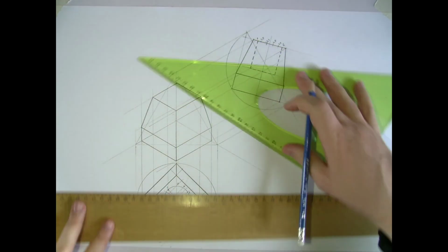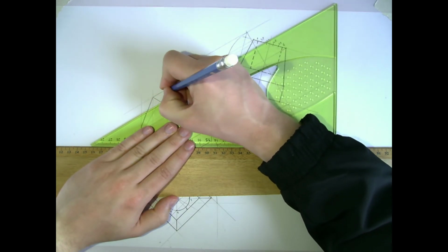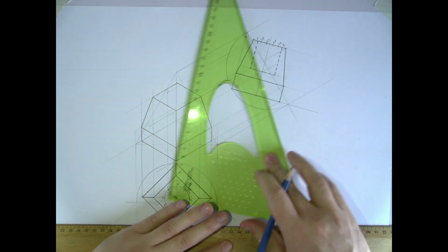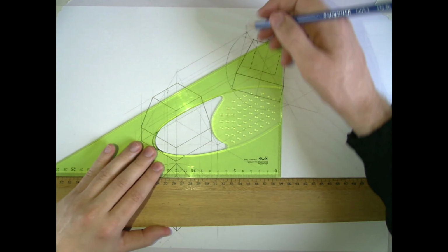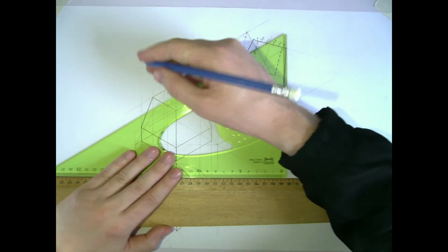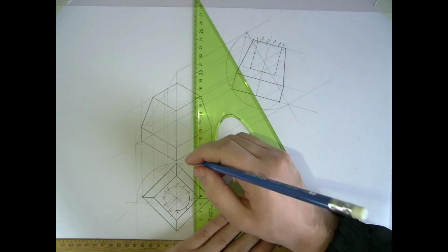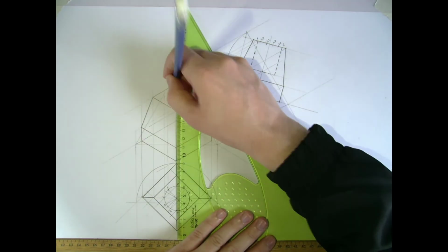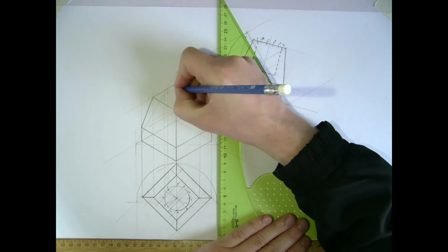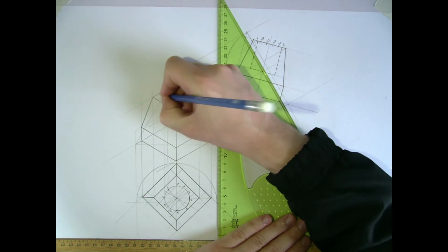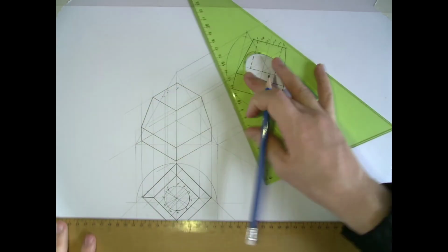So that's point 1. Project down point 1, the same point 1. That gives me a point up there. Go and do the same thing now for point 2. So point 2 is projected up. That's also projected down then from the elevation, giving me point 2. 10 can be done the same way. So 2 and 10. That's point 10. Next, do it with point 3, and so on. Continuing on doing each of these points.